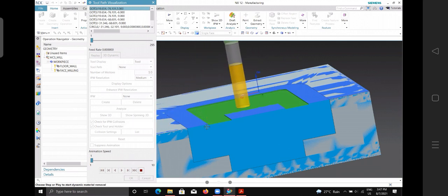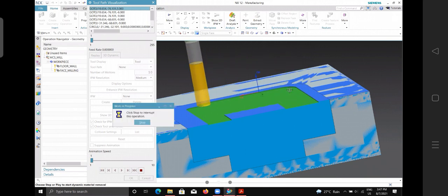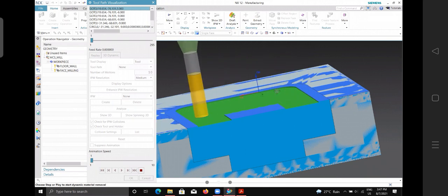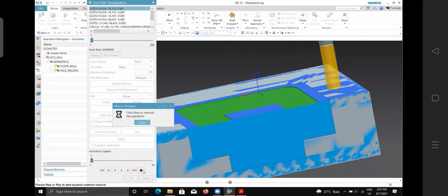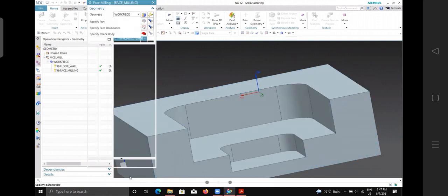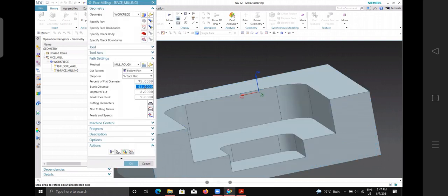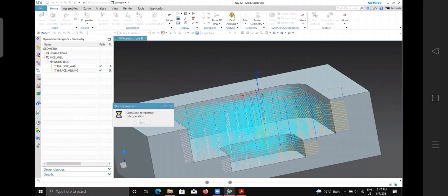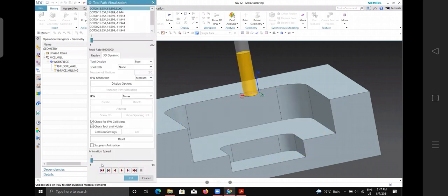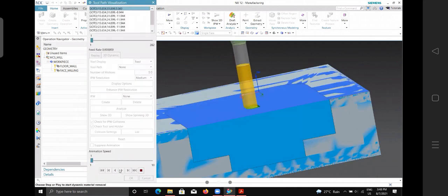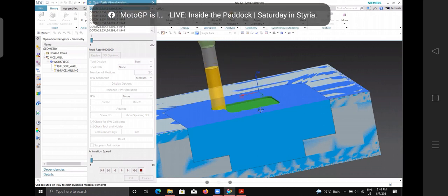If it starts cutting immediately, you can know that this is the optimum cutting position that you can give. If it's more than that, then it will not be efficient. So that is why I'm giving the blank distance from 43 to 40. Now if you click on generate and verify this, you'll see it starts cutting from the first pass.